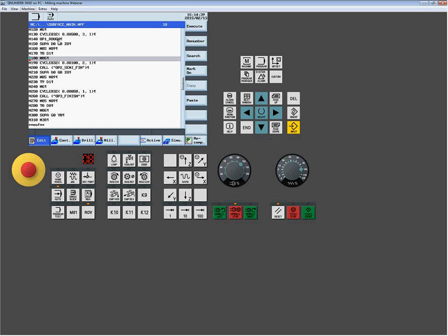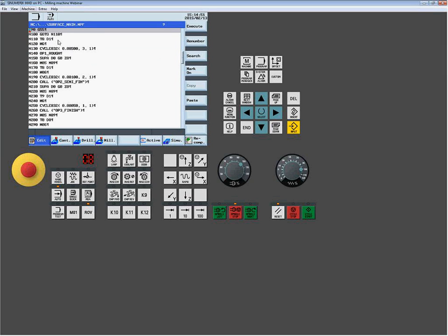For change tools, again, in this case, I'm using the same tool. I repeated the tool change statement. It's redundant, but when I'm bouncing around, it allows me to bounce a little further down the program. So I can jump over this tool, but still force a tool change down here if I have to, maybe just jump over to the semi-finishing operation, the scenario with my finish tool.